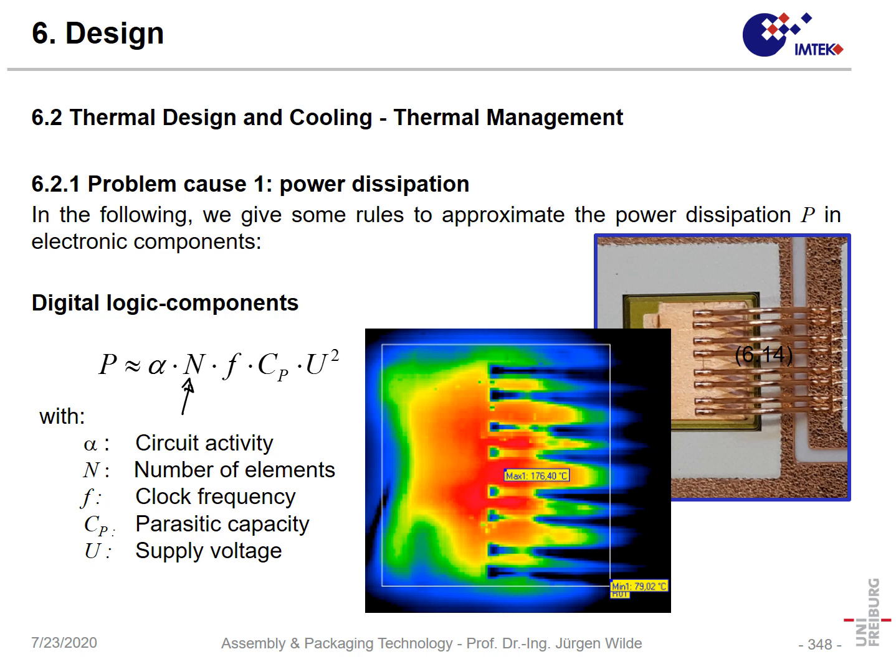It is proportional to the frequency. So the higher the frequency, the more often we turn off a bit and turn it on again. Typically, we charge the bit in a capacitor, and so we have that so-called parasitic capacities. And the larger it is, the more energy is stored. Of course, in a capacitor, the energy is proportional to the square of the voltage which we use to load it up.